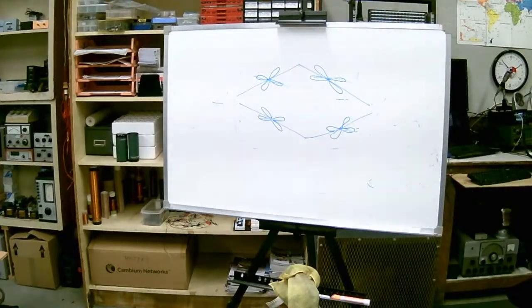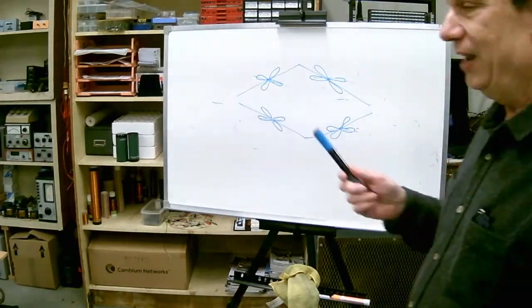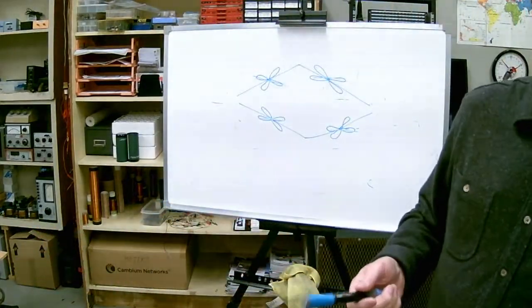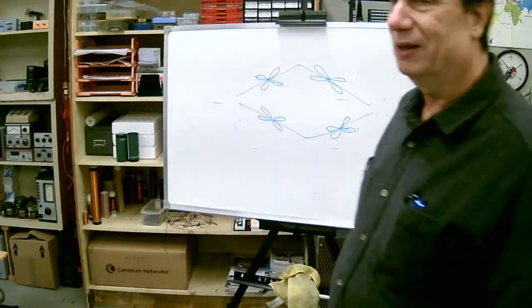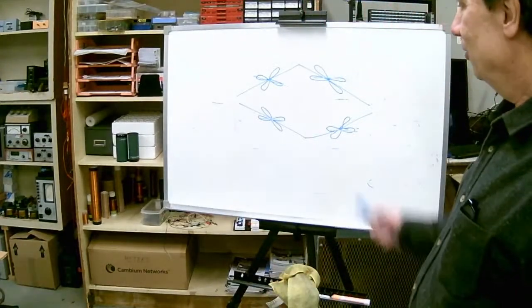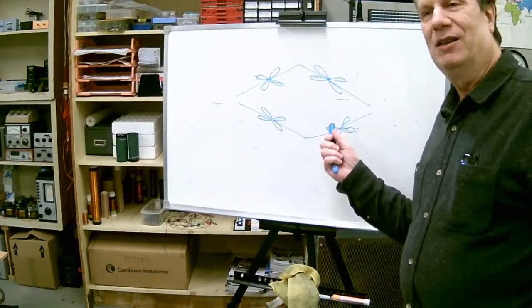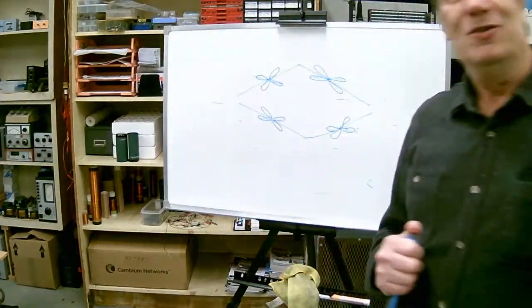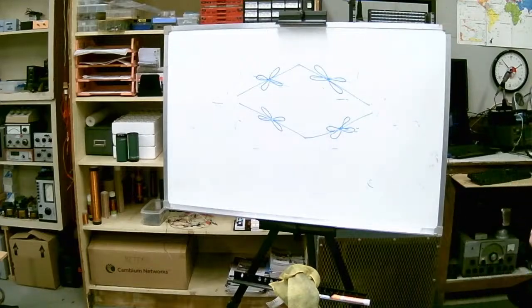As a matter of fact, AT&T, when they had some of the first telephone companies that actually used radio for interlinks, used rhombic antennas for that. So there's theoretically no limit to the gain you can get on these, as long as you don't have a limitation of real estate. You just keep making them longer and longer, and you get more gain.